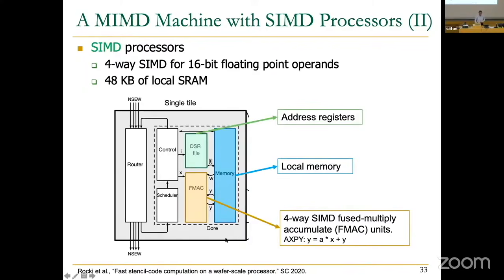And it has a local memory as well. And you can do floating point multiply and accumulate. The basic idea is you map your neural network computations to these floating point multiply and accumulate operations. Very similar to how we did with systolic arrays, except this is a SIMD machine right now. Remember that picture that I showed you when we talked about systolic arrays. You can convert a convolution to a matrix multiplication.